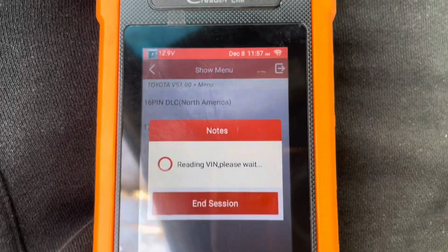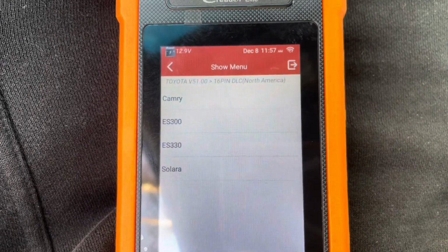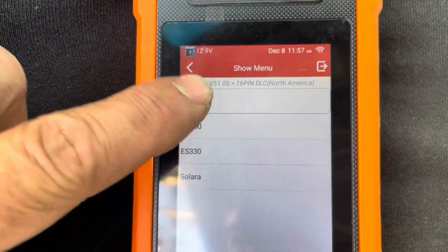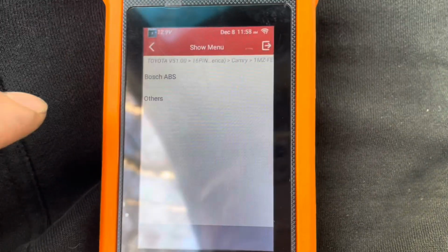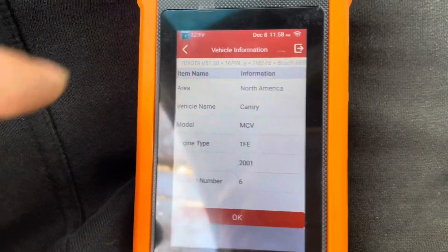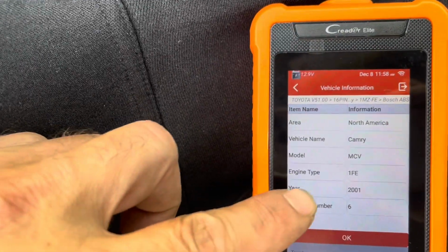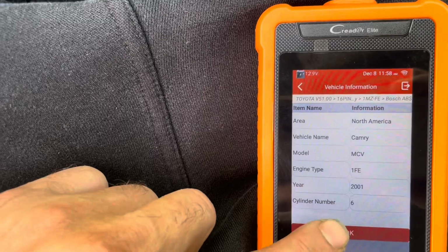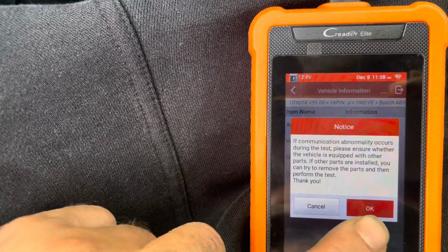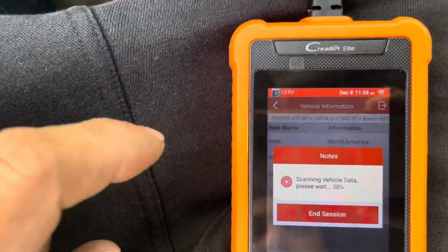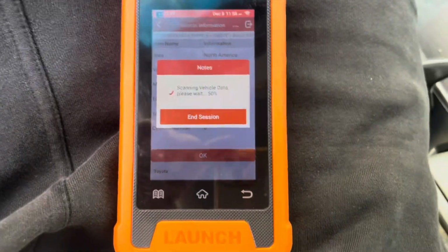My initial code indicated a fault in that circuit for that sensor. So I figured the first step was to get the voltmeter and the power probe out and test, just like A1 Auto said, to make sure I'm getting the proper power to those sensor connectors, or the switch connectors. And I figured I'd done all the troubleshooting.